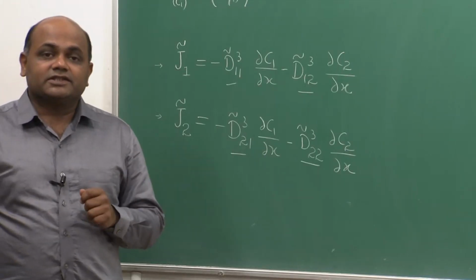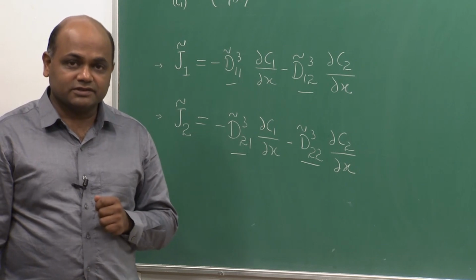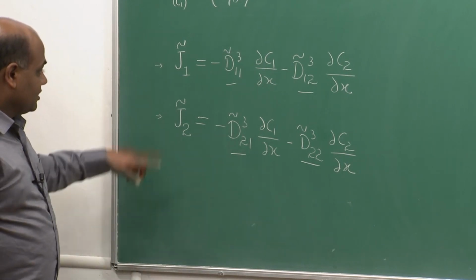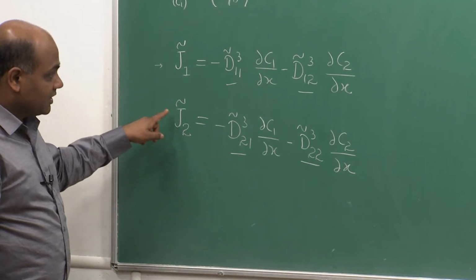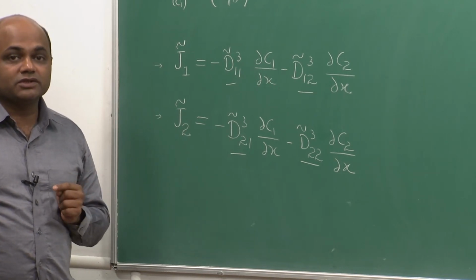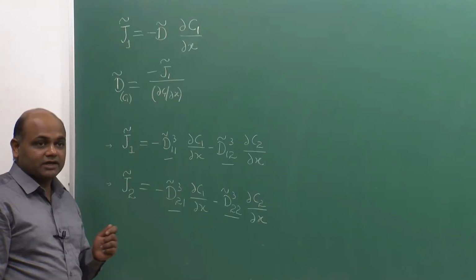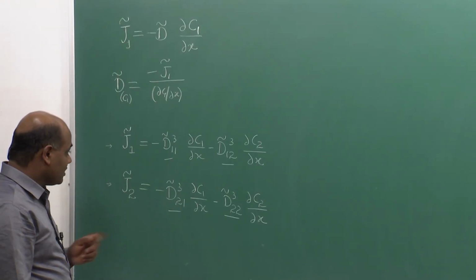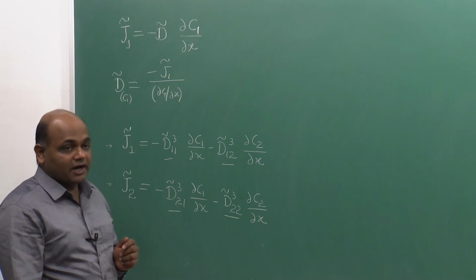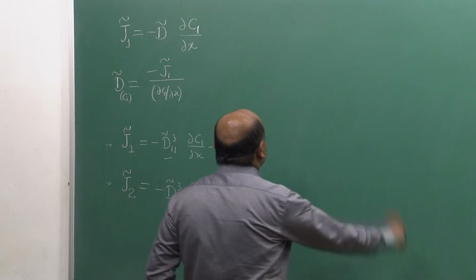And since these interdiffusion coefficients are functions of composition, we want to make sure that there will be a common composition in the diffusion zones of the independent diffusion couples that we assemble. So, Kirkcaldy had proposed originally this approach. So, let us call it Kirkcaldy's approach.